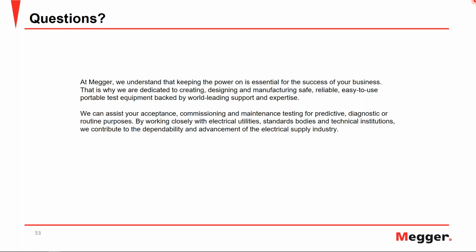You can have as high as 8% power factor values, and some of those transformers would still work just fine. So setting up the limit becomes a challenge. You can certainly run the test, but defining the limits or the analysis criteria is a challenge. And that's why I said, if you have a whole fleet of dry type transformers with similar ratings, then it makes sense to do that.